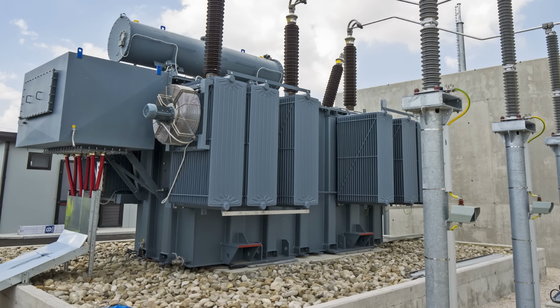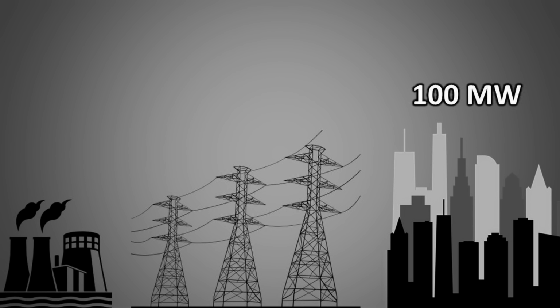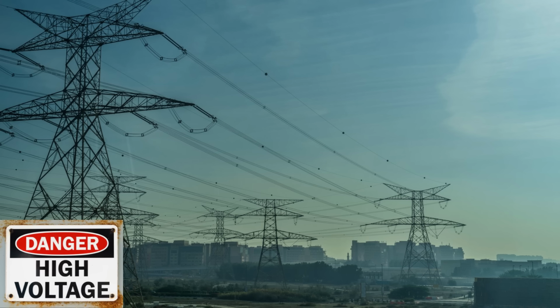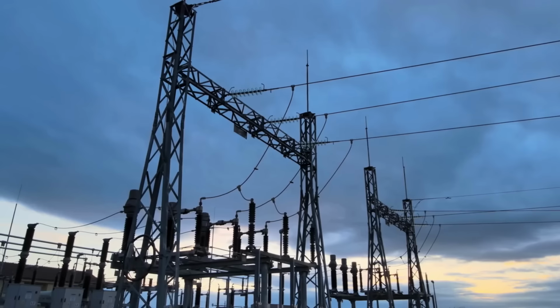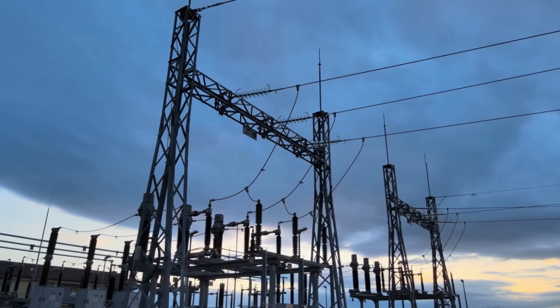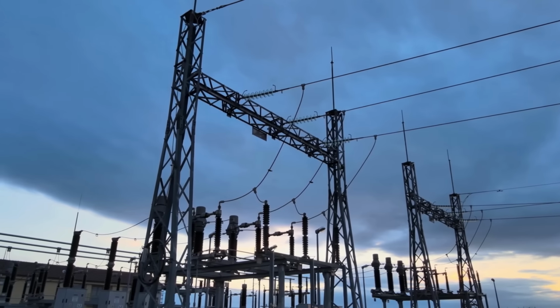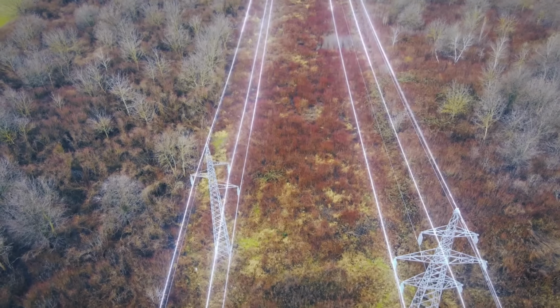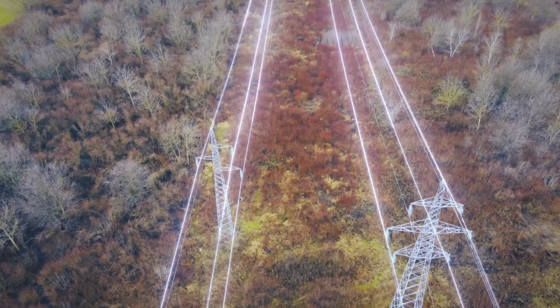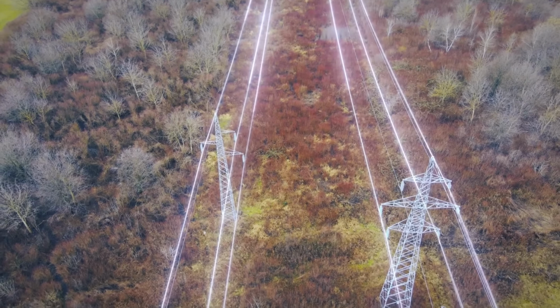The biggest advantage of alternating current is that its voltage can be increased or decreased using a transformer. DC voltage cannot be changed using a transformer. So as we discussed earlier, if we want to transmit electricity over long distances at high voltage and then reduce it to a safe household voltage near the city, we have to use AC. For this reason, all countries use alternating current for power transmission and distribution.